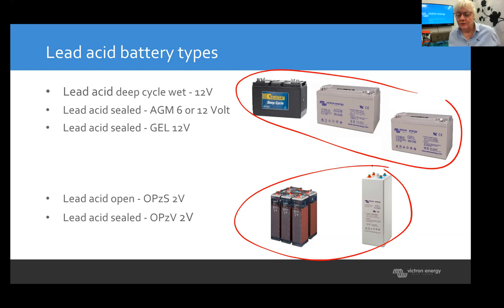So if you make a 12 volt system out of that, you have to get 6. 6 times 2 is 12. If you make 24, you need to get 12 of them. If you need 48, you need to get 24 of these batteries. The beauty is they all connect in series, and you basically decide what battery bank you want, select the capacity for that bank, and then make them into a really long series string. They come in different capacities.